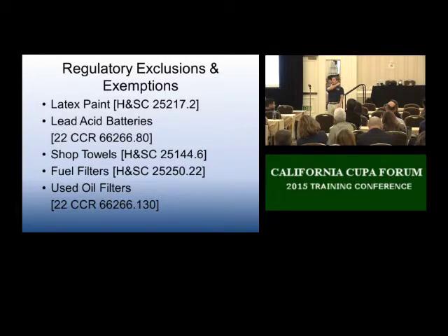And we'll run this test for four tanks. And what they do is they run a control tank. Because maybe the fish died because over the weekend it got cold and the fish died. Well, if the fish died in the control tank, we have to start all over again because all the fish died everywhere, and it had nothing to do with the waste that you put in it. So if I run a definitive test, it's about $800, and takes about a week and a half, 2 weeks. They're running 80 fish because they duplicate the tanks: 2 controls, 2 dilute, 2 at, 2 above. It's a definitive test. That's called the definitive fish bioassay.